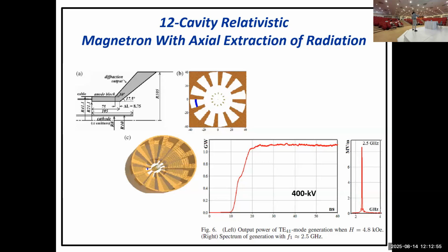Now, with these 12 cavities, they were able to extract more power, but the mode wasn't stable. It was jumping between pi mode and something in between. So it wasn't easy to control the mode. This study was just done on CST, I mean MAGIC, and you can notice that with the transparent cathode here. They tried to have 12 emitters, but there's still a lot to do about this work, and they stopped because there's no fun in continuing this type of work.